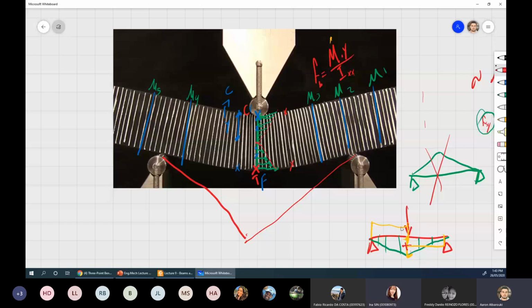Yeah. Okay, so regardless, maybe other students will be a little bit confused, so that's why. Yes, yeah, no, thanks for that, good point. But regardless, guys, let's assume, so I don't confuse you, the bending moment diagram is like that. The maximum bending moment we're trying to say is in the center. Regardless is positive or negative, the maximum actual bending moment will be in the center.